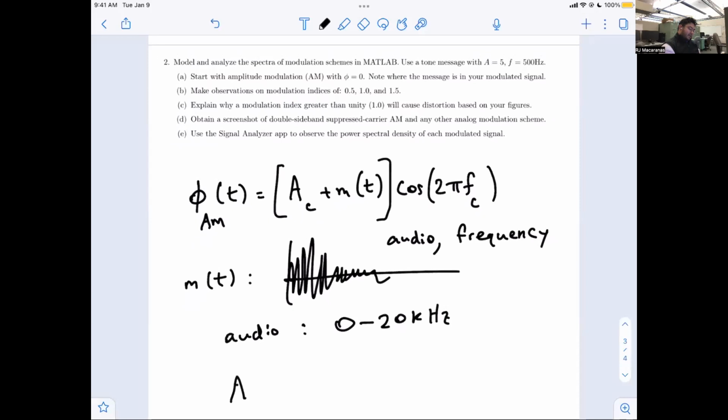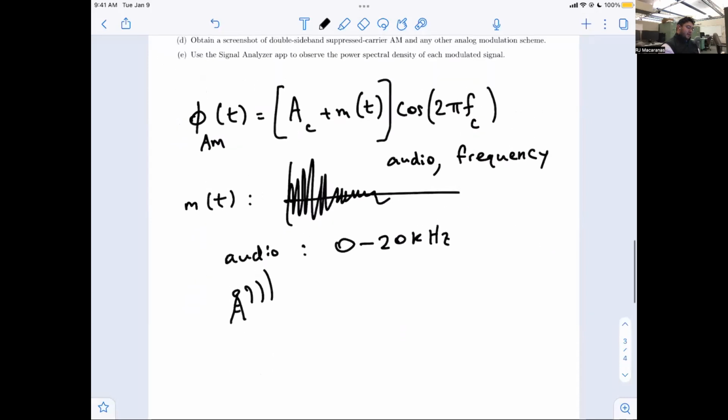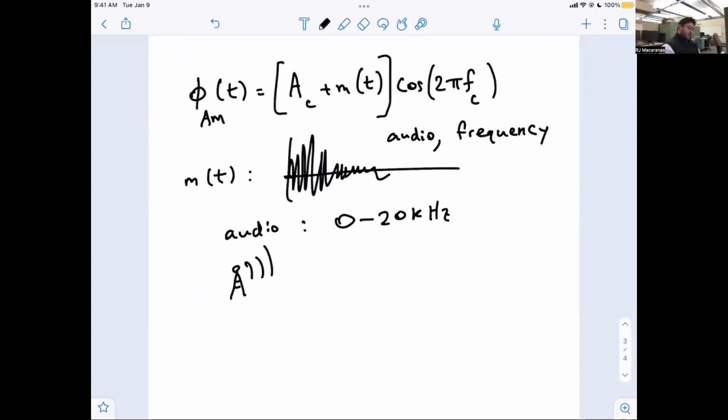So if we had just like a radio station here, we're broadcasting at this audible range, there'd be a whole mess of noise. So instead, we want to take our message, right? So Cal Poly has some radio station over here at 91.3, and this is frequency in megahertz. Then the next one down is 91.1, next one up is 91.5.